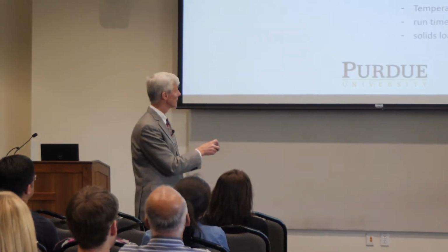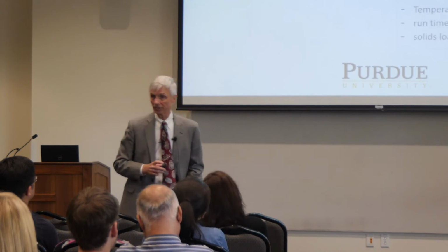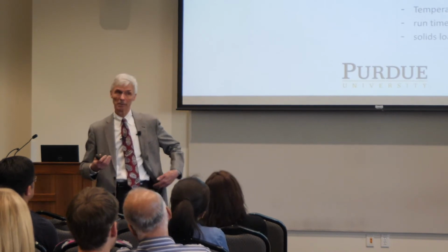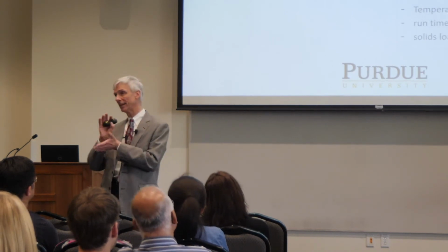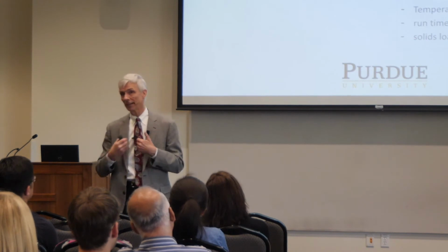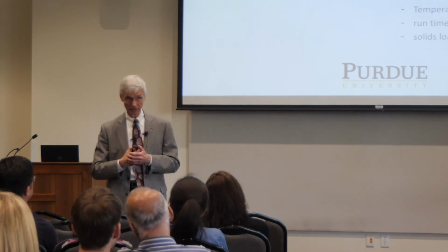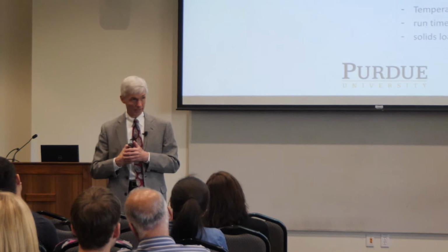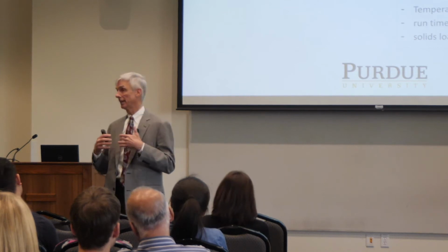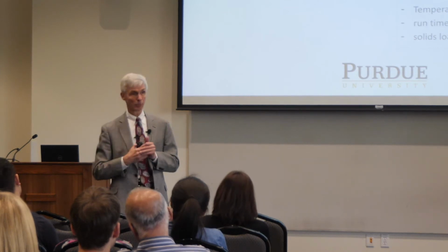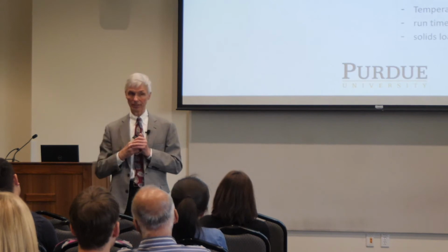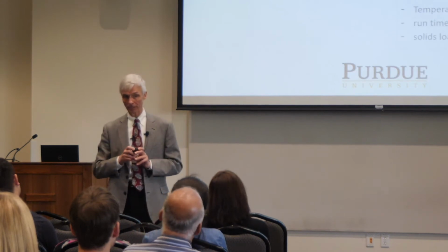And these are the conditions, 160 to 215 degrees C. Our first publications say, gee, you really want to keep the pH around 7. We found out very quickly, because of the soil that is found in some of the biomass or the silica, it naturally self-buffers anyhow to 4 to 7. So you get a little bit of degradation. So you don't have to add any chemicals either.